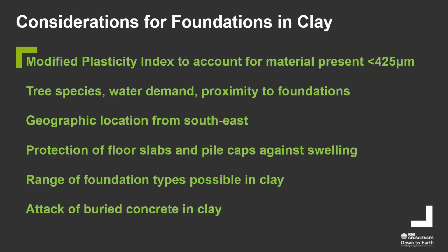So are we talking immediately going down the route of suspended floors? Well, probably, unless we're a long way away from the tree and we're happy, through moisture content testing, that the clay hasn't been impacted. By site investigation being thorough, one could actually check the current state of play of my clay in terms of its moisture in depth below the intended floor slab level. And then are there other foundation types we could use? And indeed, what about buried concrete?